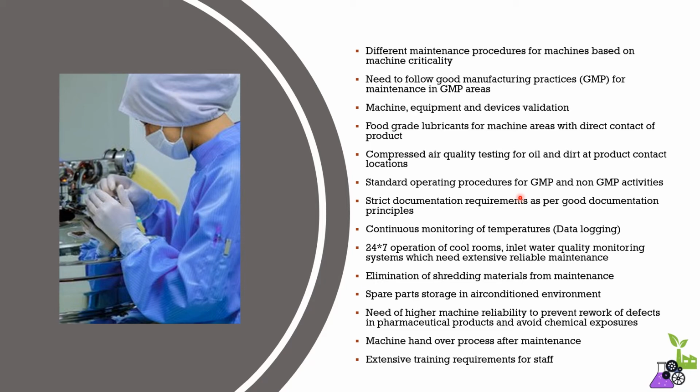Again, compressed air might carry different kinds of contaminants like oil and dirt. So it's a usual practice in the pharma industry to test such compressed air sources at the points where it is having direct contact with the product.